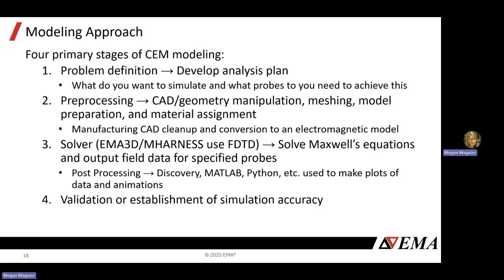Then you move into pre-processing. This is where you start with your manufacturing CAD, and then you simplify it into a suitable electromagnetic model. You mesh that model, you make sure your mesh looks good, and you prepare your model with material assignments. And then after that, you move into the solver phase. This is when you're just running the simulation.